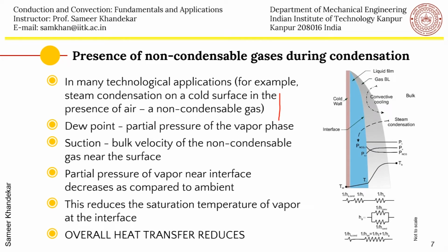I hope you remember the fundamentals of psychrometry. As the temperature of the cold wall becomes colder and colder, the dew point will be hit when the temperature becomes lower than the saturation temperature corresponding to the partial pressure.